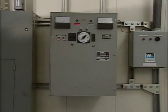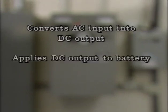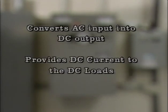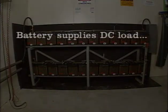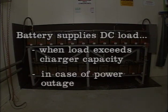A battery charger serves several functions in a typical substation DC system. First, it converts an alternating current input into a direct current output. Second, the charger applies the direct current output to a battery and controls the output in order to keep the battery fully charged. The charger also provides some or all of the direct current to the DC load. The battery supplies the DC load only when the load exceeds the capacity of the charger, or when a power outage prevents the charger from providing direct current to the load.